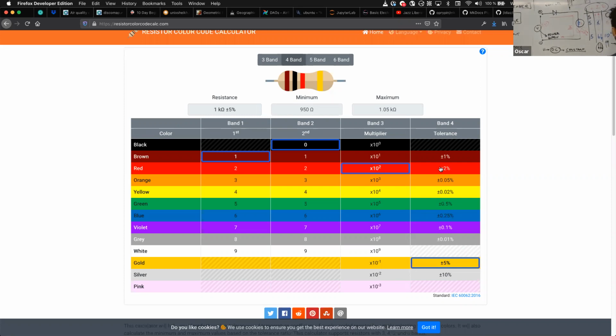This is the anode, and this is the cathode. Current only goes that way, but doesn't go this way. It only allows current to go in this direction. What do we use this for? Normally for protection, so that there's no reverse current going into our power supply and we kill our computer or our charger or our Arduino or things like that.